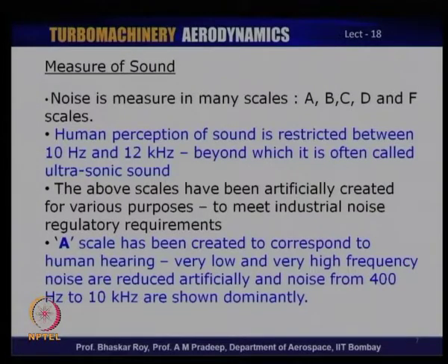So, many of these scales conform to those regulatory requirements used in the industries, and F scale typically conforms to a flat scale, where all the noise that is coming out is picked up on a 1:1 basis. So, the entire noise from 10 hertz to 20 kilohertz is picked up in the F scale. So, those are the scales that are typically used in noise measurement.